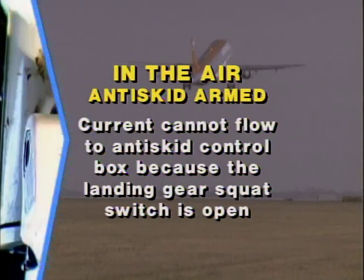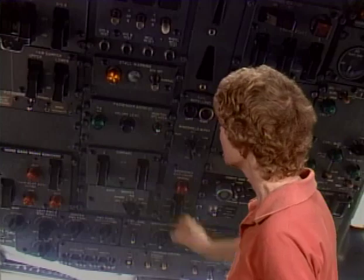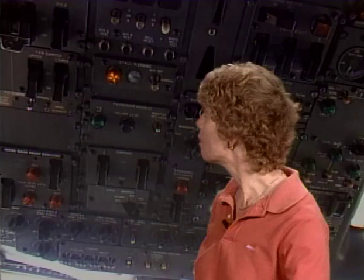It is activated or armed in most installations by a switch in the cockpit. And in a 727, that switch is in the overhead panel above the captain and the co-pilot. So you've got a switch there that you turn on before landing. Now, if there is a problem with the anti-skid system, if there's a system failure, or if you've simply turned off the system, there will be a warning lamp that lights that tells you that the anti-skid system is not activated for one reason or another, that it's either turned off or that there has been a system failure.